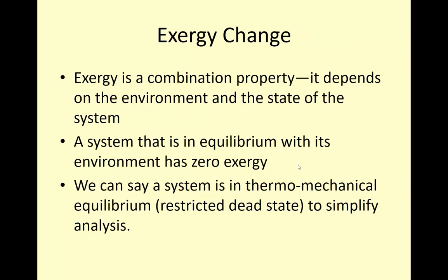So exergy is a combination property because, as we mentioned before, it depends not only on the state of the system, but also the environment surrounding the system. So the environment will determine your dead state and the temperature and pressure at which you would be in thermodynamic equilibrium. So anything that's in equilibrium with its environment has zero exergy.